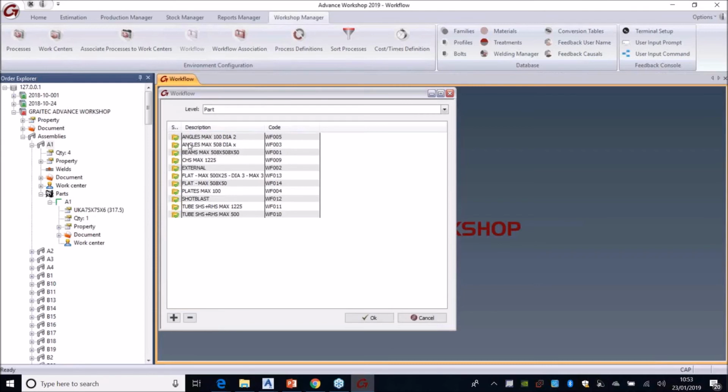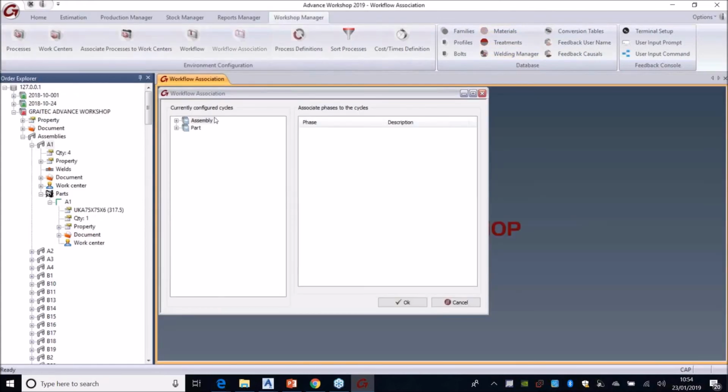And then here we have another process for another machine, angles maximum in terms of parameters and size, 508 millimeters, and there is no limit to the amount of diameters this can handle. So I'm basically applying the restrictions based off of the machines that I have in my shop.